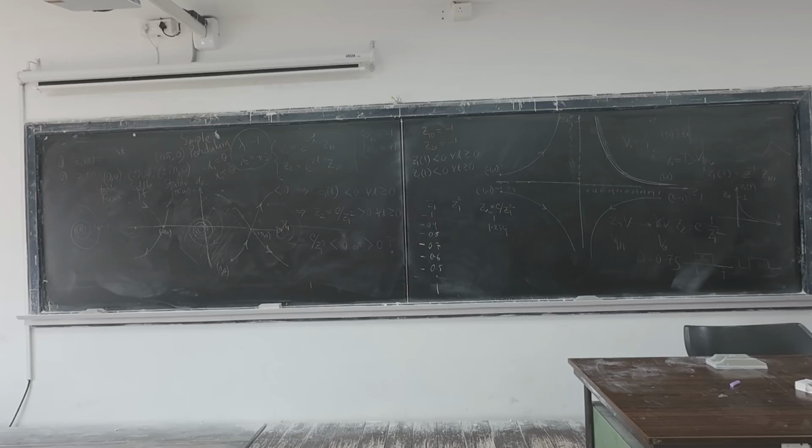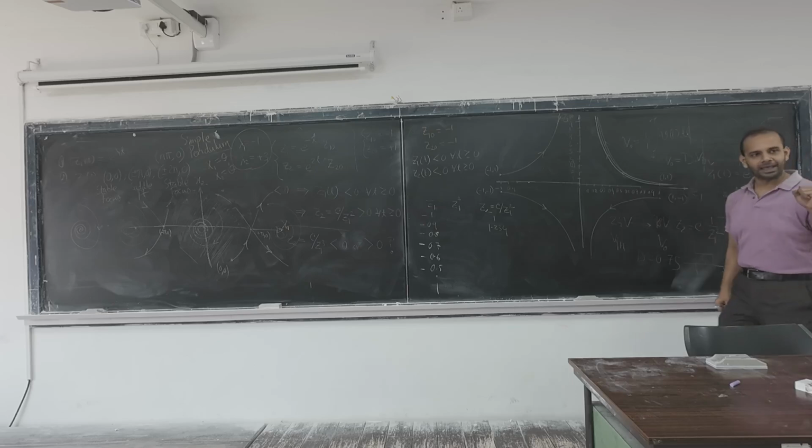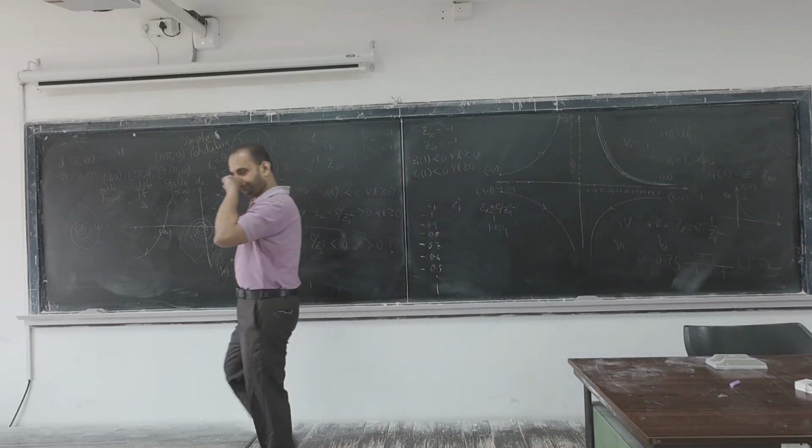If it is step up, that is called a boost converter. They are also the same thing. How much you want the voltage to be, you have to decide the T on and T off. So once again, corresponding to T on, you have a stable operating point. Corresponding to T off also, you have another stable operating point. And we force the system to switch back and forth between these two, so that ultimately we get an average of the value. If we don't change the switch, then the averaging won't happen. So it would be either equal to V in or equal to 0 for all time, but that is not desired.